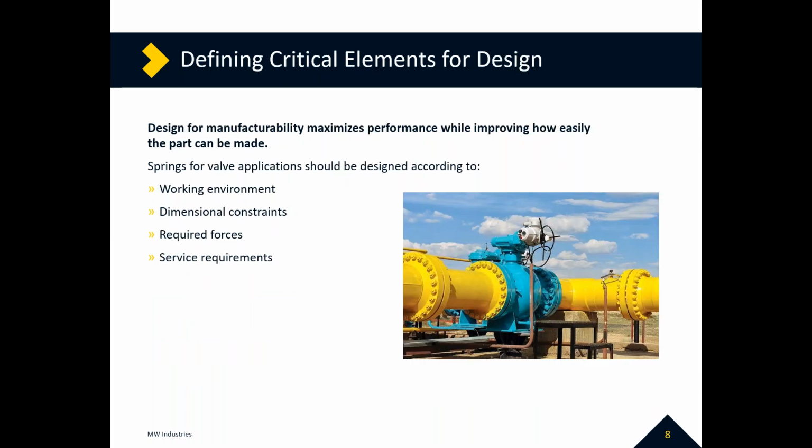We also want to define critical elements for the design. There are 4 of them. The first is the working environment. We really want to understand where the spring is used. As I mentioned earlier, relief valves or valves work in gas applications and definitely liquid applications. We want to understand what is flowing through there to help you get the right material and the right stress that material should be at in that application.